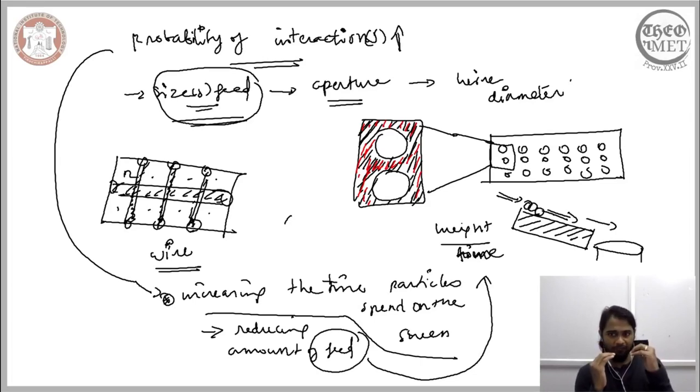And when you have particles spending a sufficient amount of time, then essentially the probability of interaction increases. So the probability of interaction not only between the particles increases, the probability of interaction between the particle and the perforated screen increases, thereby increasing the chances of screening.